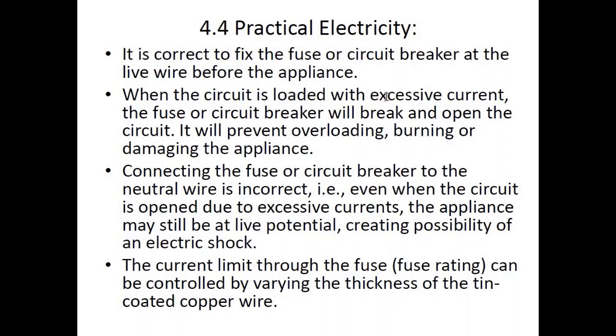It is correct to fix the fuse or circuit breaker at the live wire. Always remember, fuses or circuit breakers are connected on the live wire, never on the neutral wire, and they are connected before the appliance so that excessive current can trip them and does not damage your costly appliances. When the circuit is loaded with excessive current, the fuse or circuit breaker will break, preventing overheating, overloading, burning, etc.